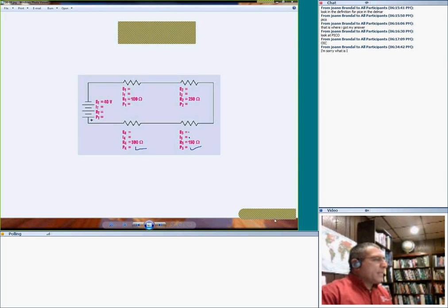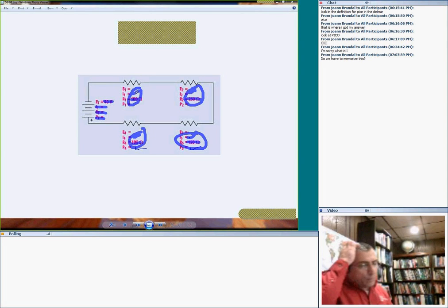So the important thing when you deal with the circuit, before I give you a break, I know you're due for a break, is recognizing that you need to add these resistors as your start point, divide the voltage by them so you can get the current, and from the resistor and the current you get the power. The current is the same in each one of these resistors. Now if I have two known things, I can find the two unknown things.